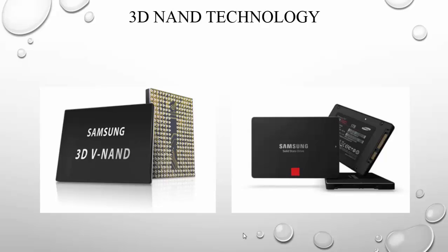Because last year, Samsung announced 3D VNAND technology, which is going to be used in Samsung solid state drives. So 3D is like a three-dimensional NAND technology. Three-dimensional flash memory is emerging to fulfill the ever-increasing demand of storage capacity. In 3D flash memory, multiple layers are stacked to increase bit density and reduce bit cost of flash memory. However, the physical architecture of 3D flash memory leads to a higher probability of disturbance to adjacent physical pages and greatly increased bit error rates.